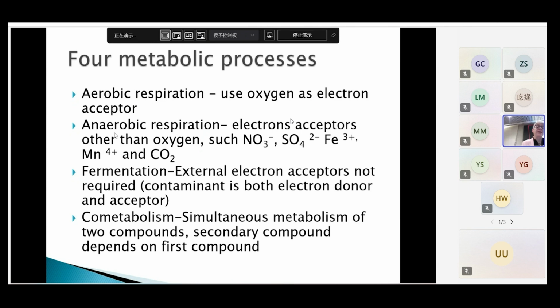So things like soil flushing, soil vapor extraction are fairly low. Phytoremediation costs are pretty low. Things like thermal desorption are fairly high. Vitrification, where you're using a lot of electricity, basically melting the soil, is also a very high cost process.